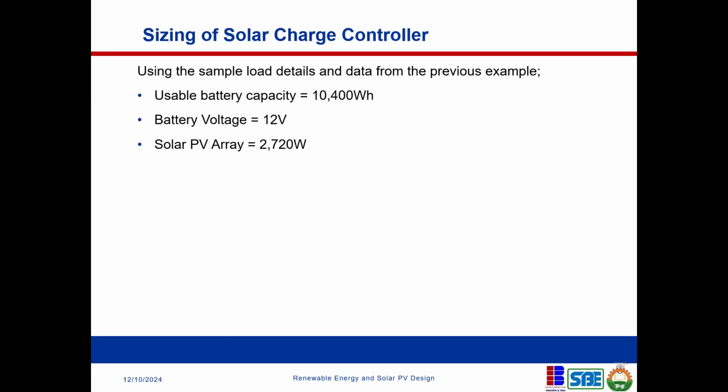So that's what a charge controller does. If you remove that charge controller, the battery is going to be damaged. And that's why it always comes in between the solar panel and the battery. If you have a design that does not have a battery, then you don't need a charge controller. I say that again: if you have a system that does not have a battery, then you don't need a charge controller. Okay? So that's what a charge controller does.